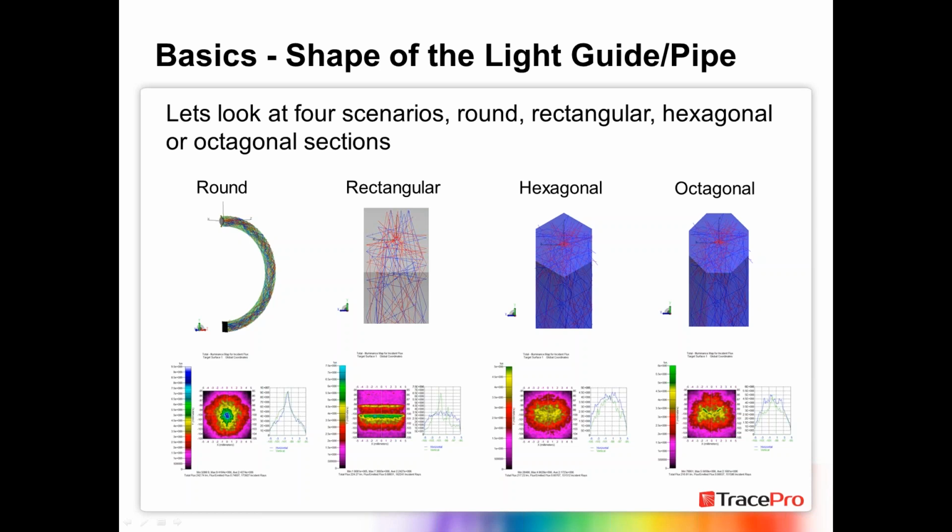But what's happening here is a lot of the light is emitting outside of the pipe because I'm trying to get a uniform output in a square pattern where the light's bouncing around and mixing, and it's very difficult to have it go out where I want it with the correct pattern, the correct efficiency, and the correct lit appearance. That is causing me some problems in getting a higher efficiency. So I'd say about 50% would be the max that you'd probably see, because I definitely need a textured surface, and that also has me losing light to my target because it puts it out into a full angular area and not just into the target area where I want the square.